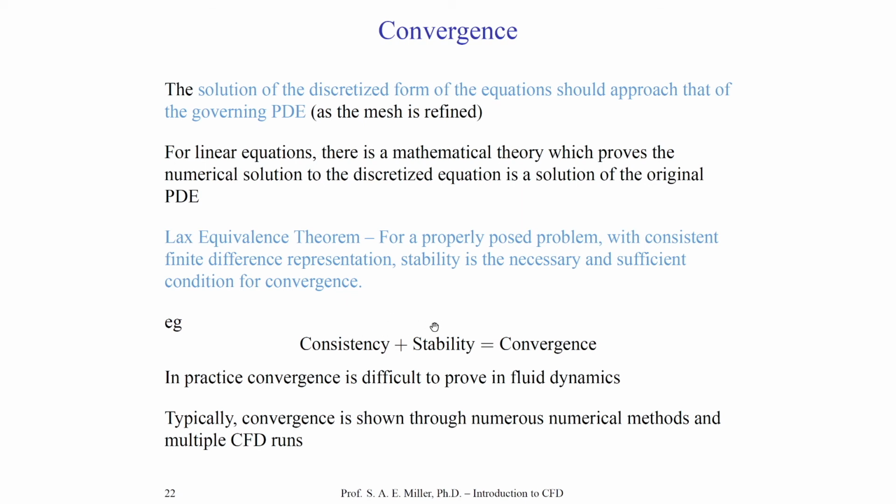If we have these two properties, then we have convergence of our scheme. And of course, with time marching or iterations of the solver, we are guaranteed to go towards a solution. Now, depending on how you set up the problem, you may not have stability. The grid itself may not let you have consistency. This is the importance of having an excellent computational grid, choosing the right numerical scheme, and meeting the requirements of the CFL number. If you do these two steps correctly, then of course you're guaranteed convergence.